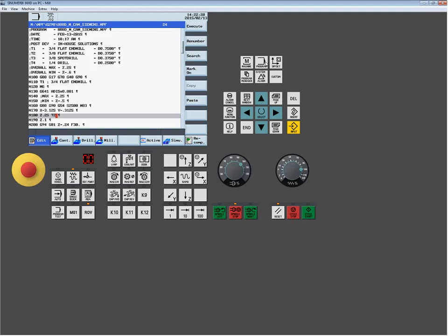However, this post was written for a machine that has a random style tool changer. So what this cheat code right here is doing is it's actually prefetching the carousel for the next tool. Unfortunately, this machine that we happen to be on is a carousel tool changer, meaning I can't randomly set up my tools. Well, you're going to find that depending on how they commission the machine, this can create some interesting results.